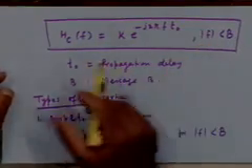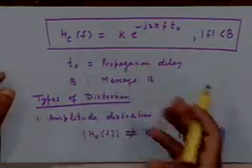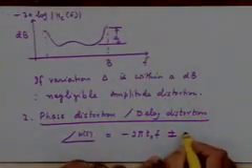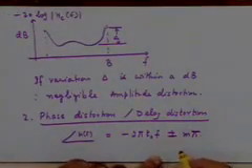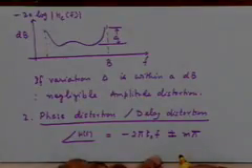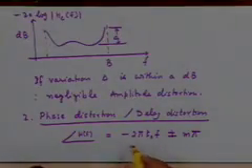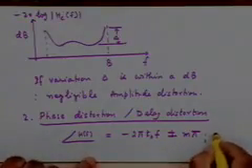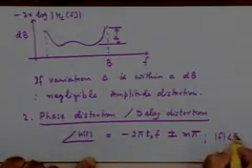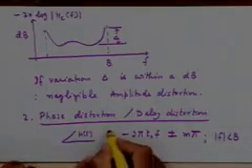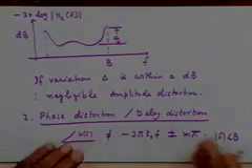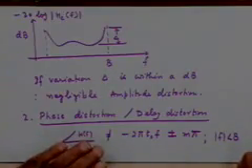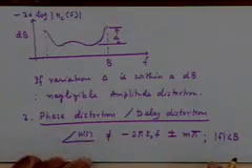So it does not really make any difference to the basic phase characteristics. So the required condition therefore really speaking is this plus minus m pi, right. So if this is so, there is no distortion over the bandwidth of interest for mod f less than B. If this is not so, that causes phase distortion or delay distortion, right.